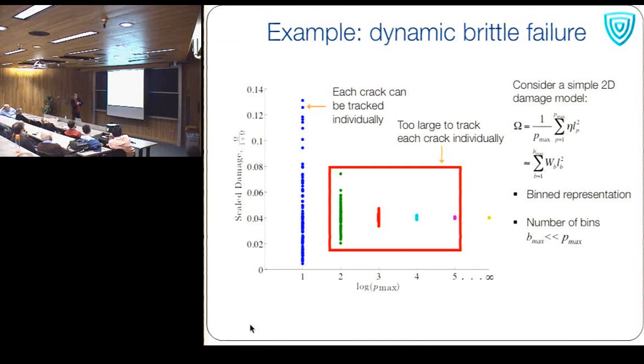We already talked about the fact that we can't go out to infinity. Infinity was like a finite element bigger than thousands of kilometers squared. That's off the table. We know variability matters. We could have a finite element mesh down at a scale where there's maybe 1 to 10 flaws per element.